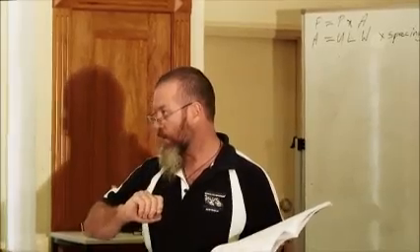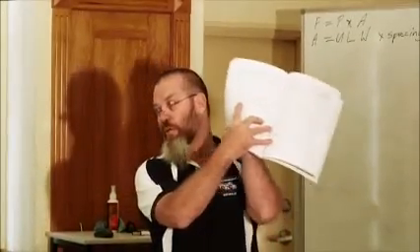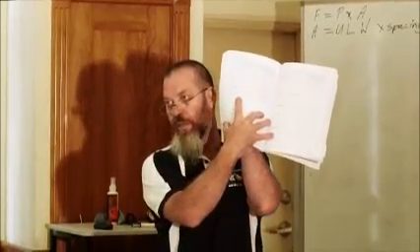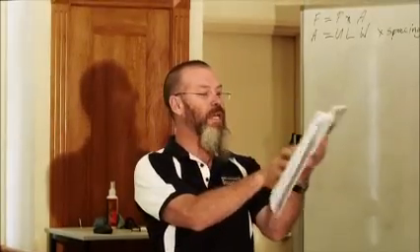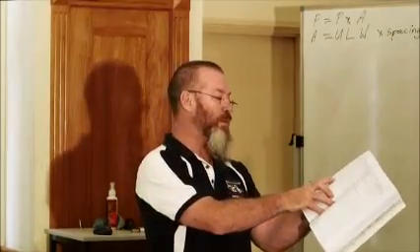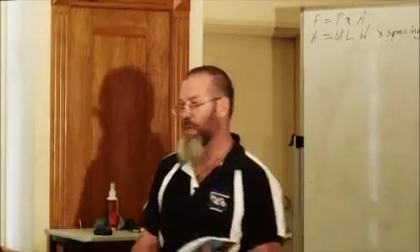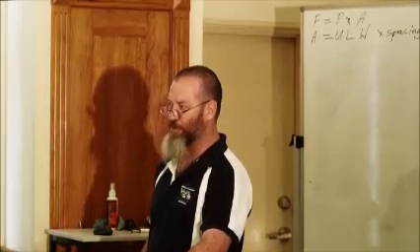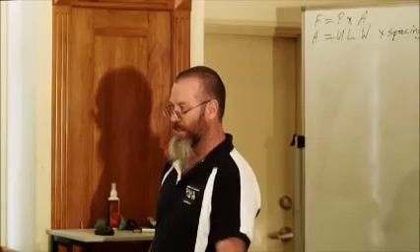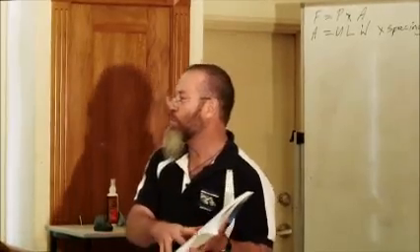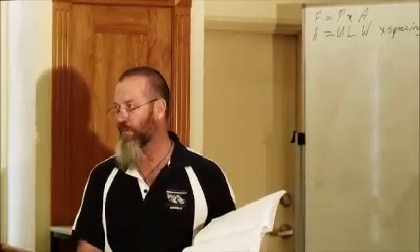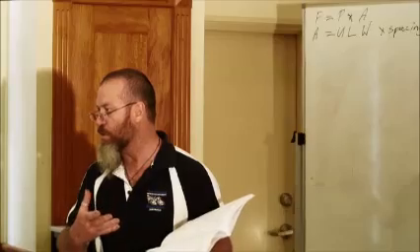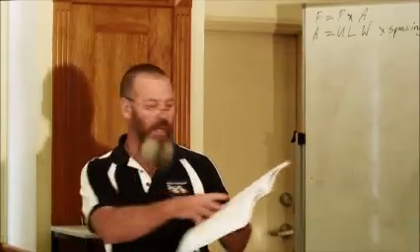But look at this little note over in the corner. See the note there under my finger? What it says is 2 screws shall be used only with 75mm wide battens. Now that's a mistake in itself. There's a typo there. Cross out the word screws and write nails for a start. So you can only use 2 nails in a 75mm batten. So we can't use that connection. We have to go down.